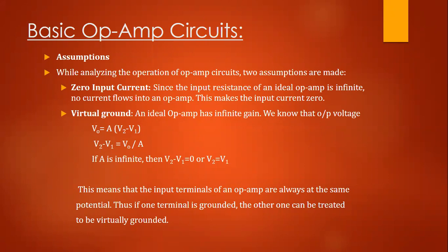So we know that op-amp is a very high gain amplifier. Whenever we want to use this op-amp as an amplifier, we need to control the gain of the amplifier. To control the gain of the op-amp, we need to go for negative feedback. That means we need to feed a fraction of the output signal back to the input. But to make the feedback negative, we must feed it back to the negative or inverting input terminal of the